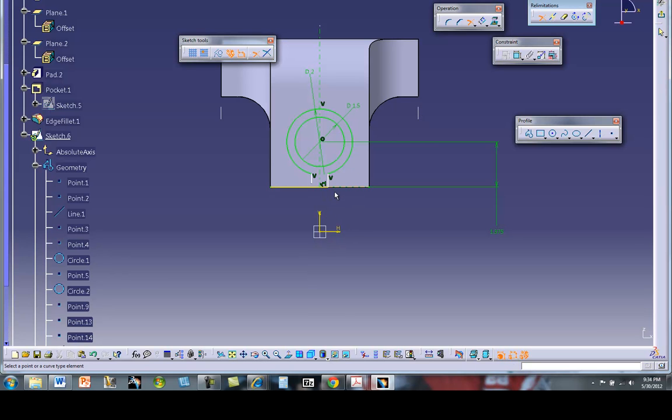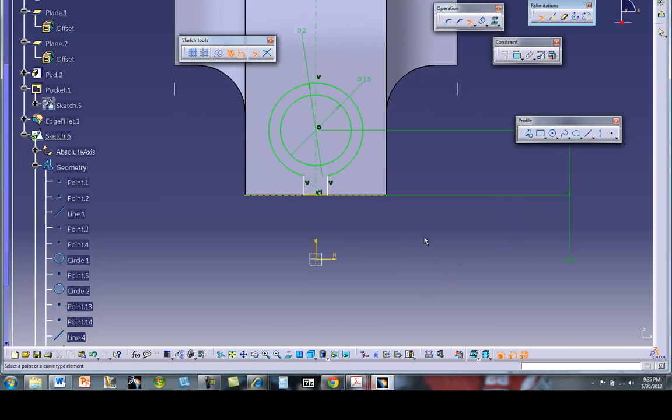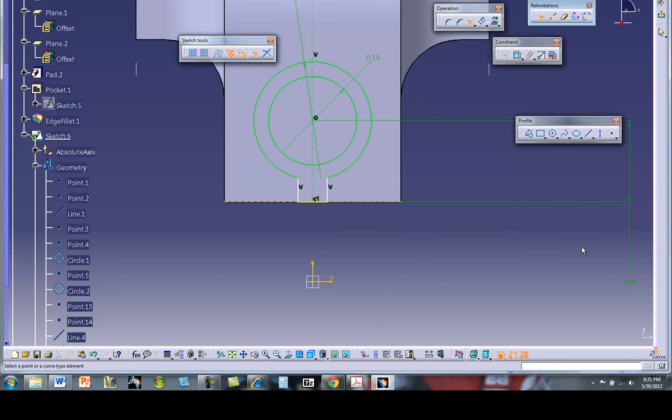Now notice that changed from a construction line into a standard line. When you use that trim, it's going to take the default of that value in here. Control Z, I did not want to do that. Grab the long point, I'll grab this then to there. Now, through my trims, I lost some of my sizing here. So let's pull these values in here a little bit so they're easier to see. Okay, I'm going to pull this over so it's over here in the blue area, easier to see.